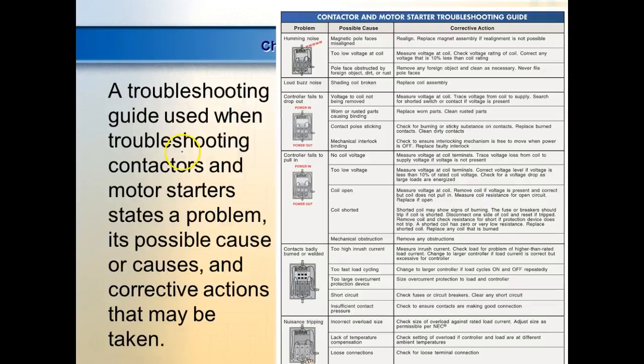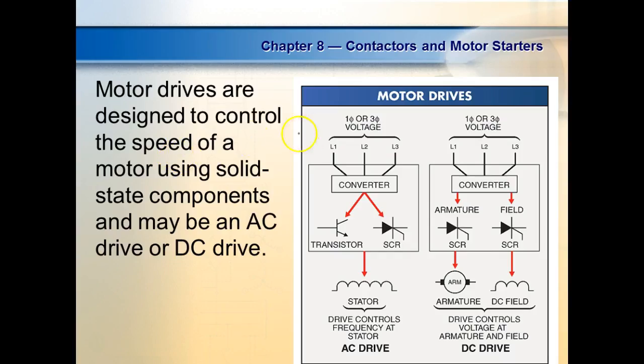So I guess this is on this chapter, so y'all make sure y'all bring in y'all's, let's look at this real fast. Motor drives, DC motors, we're going to either drive them with what? Transistors or SCRs. Transistors we use for low power devices, low power motors. That's not always true, a lot of times we'll hook these things in parallel. I've seen some DC drives where they'll have like 8 transistors connected in parallel. That's pretty expensive. Normally on your big high power DC drives, you normally use what? These things called silicon controlled rectifiers.